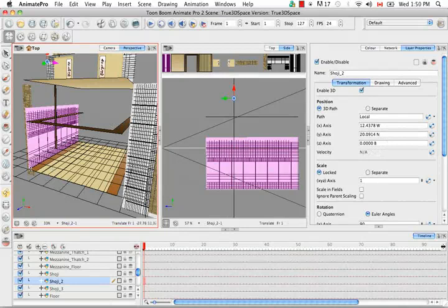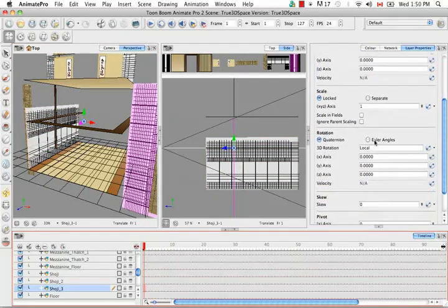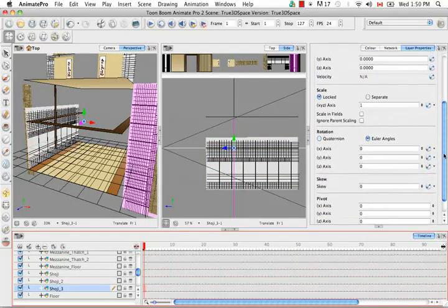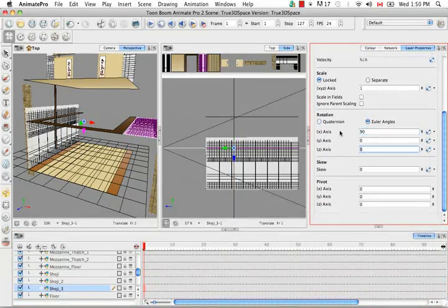And one other thing is we have to make sure that our wall and our floor, so where two planes meet, actually intersect. And that's because even if you have them microscopically close together, you'll always be able to see a white line, a white space that appears between two planes. So you actually have to have a small overlap within the corners. So let's just do our second shoji very quickly. Euler angles, 90 here, and 90 here as well.